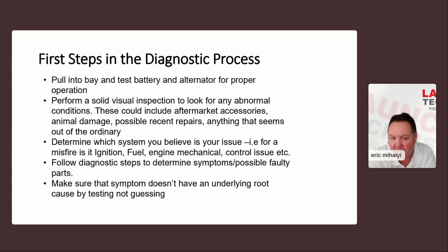And then the last thing is, I see a lot of times that people get a car come in with a misfire, say they got P0304, cylinder 4 misfire, and they're like, oh, I got a burnt-out coil. It needs a coil. Maybe I'll recommend all four spark plugs. Great. That's awesome. Okay.